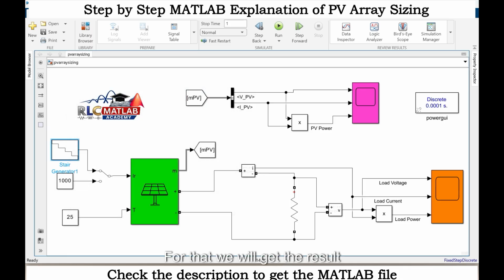For that we will get the result. As the irradiance level is decreasing, the power will also decrease. This is the constant irradiation. You can select the manual switch to change your details. So this is the constant block. You can select the constant block and enter the details.